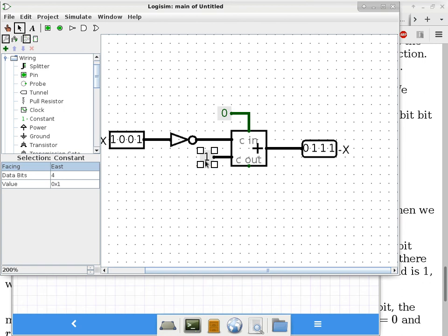You don't want the input width to be different from the output width. So the extra carry is its own pin. Usually it is not a part of the result. That's why, in this particular adder, carry out has its own port, and the sum is a different port.